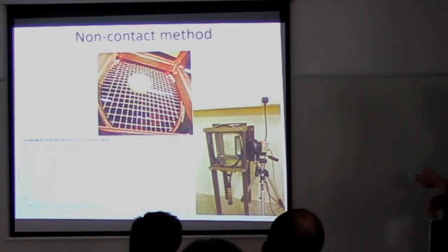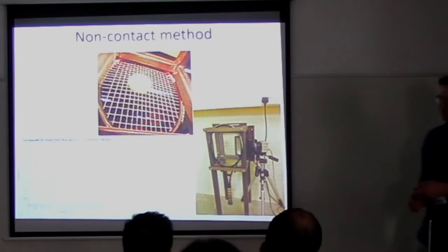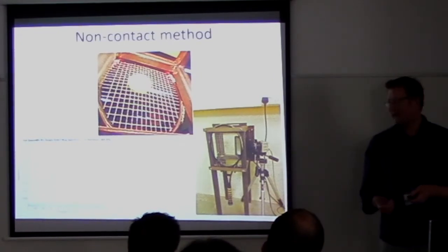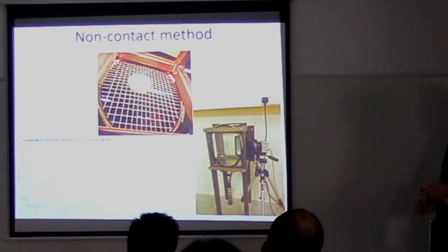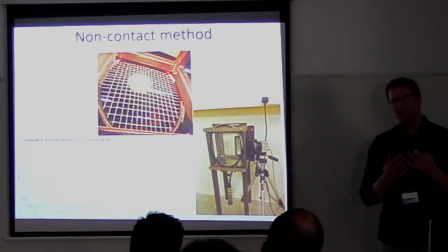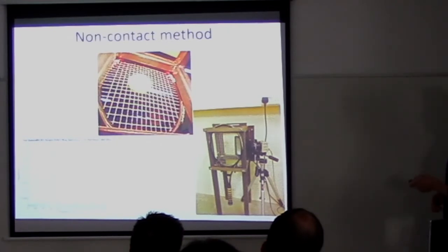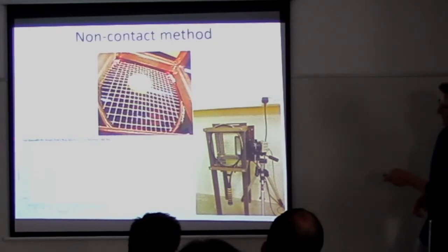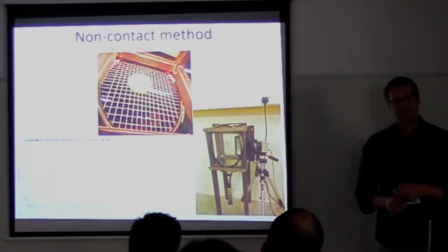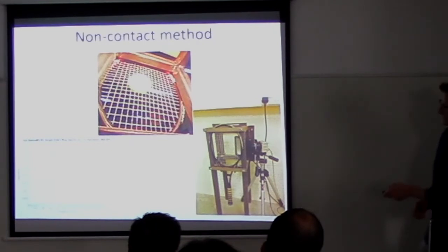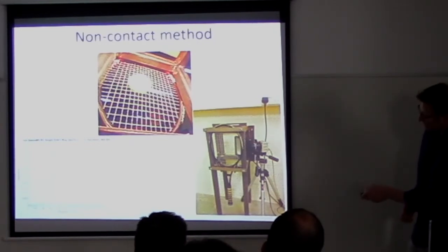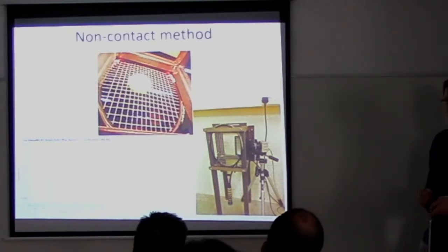So we used the same camera, a slightly different rig, because the uncertainty was, will it actually capture the displacement of the string bed completely? And what we found is we were able to adjust the settings widely to finally end up with a setting which could give us a complete response. And then we put that through some FFT, some Fourier analysis software, and it's then giving us a single frequency of almost 600 Hertz. So this is actually more in line with what we'd expect.